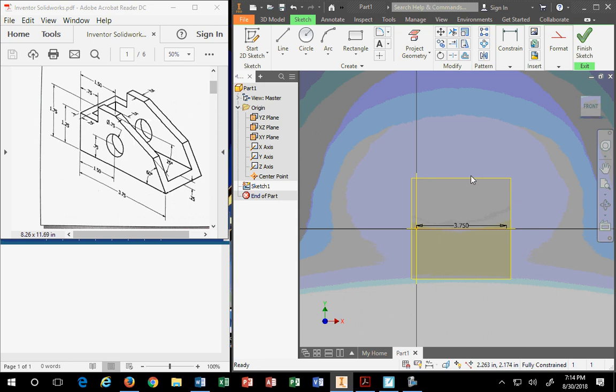Got it? So when you're done drawing the line, hit the Escape key. Earlier today I was doing AutoCAD, so of course the first thing I hit was the space bar, because we all do, don't we? Even though it's an Autodesk product, the same maker as AutoCAD, it still has its own little idiosyncrasies.